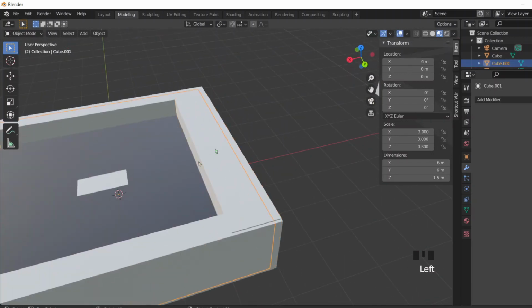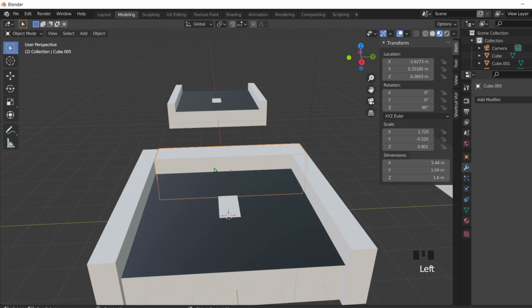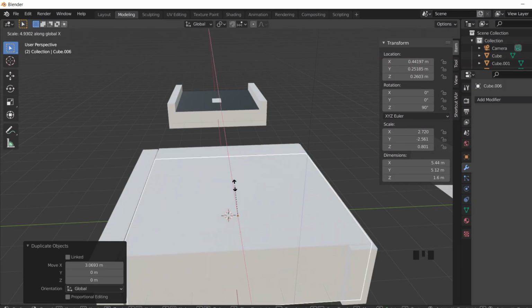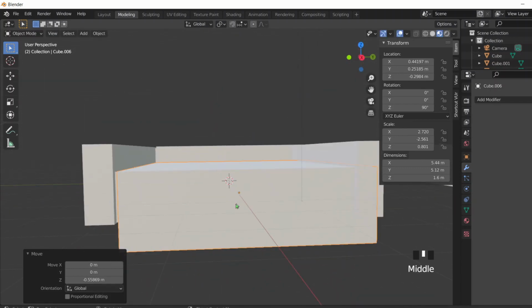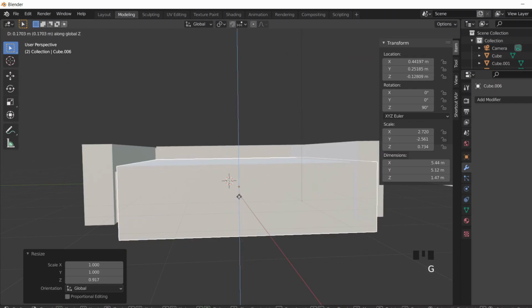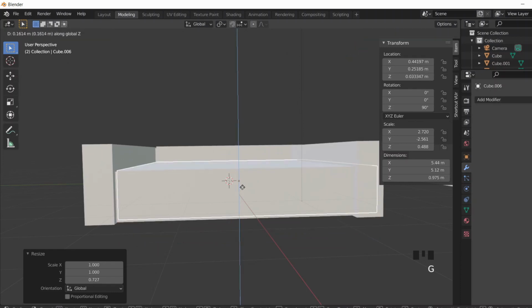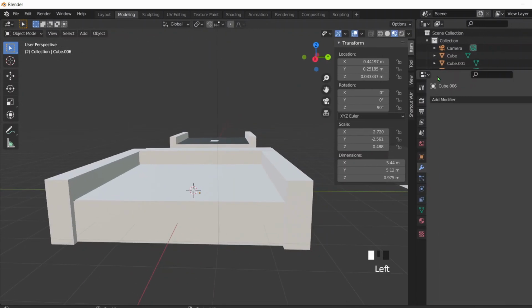And then from there, we just need our last shape. So all we would need to do is cover this base. Do Shift D, and then move in the X, and scale it in the X, so it's like that, and then grab and constrain its movement to just the Z. Scale roughly, make it thinner. So you'll notice that this shape roughly covers the shape of our static mesh. So these would be simple collisions you would want if this was being used as a prop or something.